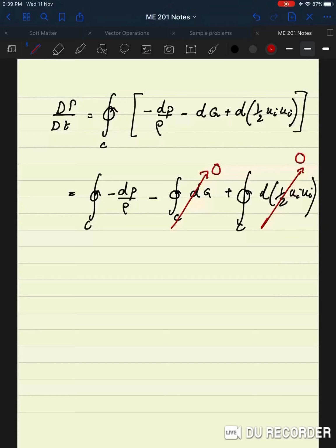So sort of obvious. Now if rho were constant, then you will be able to just take rho out and you have minus dp, right? But pressure is also a single valued function. So if pressure is a single valued function, then this is a special integral because you are doing it over a closed contour, this would go to 0, if density were constant.